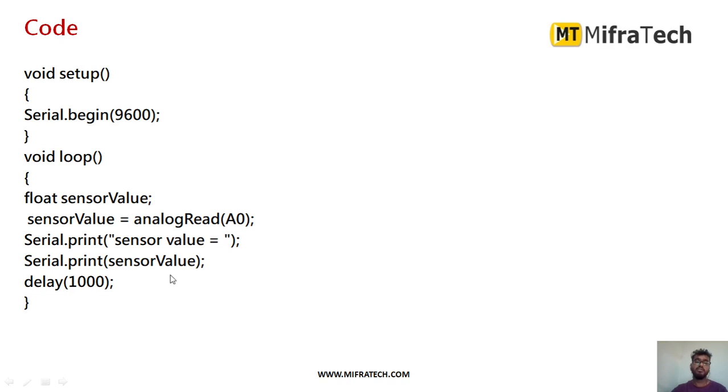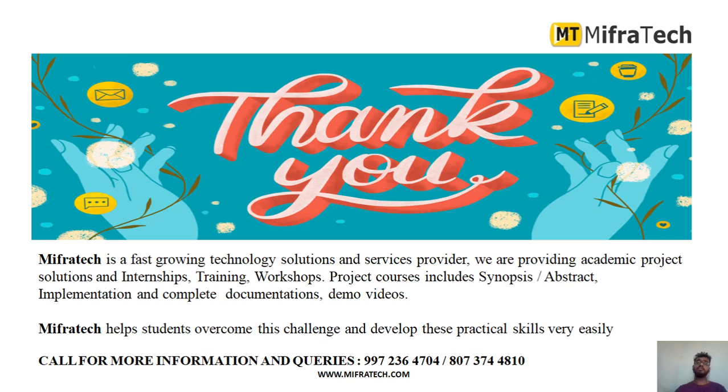If I execute this code and dump it into the Arduino microcontroller, the gas sensor will detect whether any concentration of gas is there or not, and send the data to the controller. Like this, you can easily interface this with the Arduino Uno microcontroller or any other microcontroller. In this way, you can make use of this MQ7 gas sensor to detect combustible gases, particularly those containing carbon monoxide.